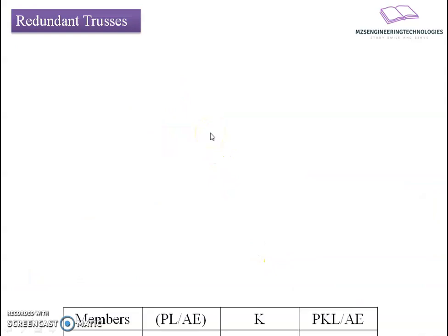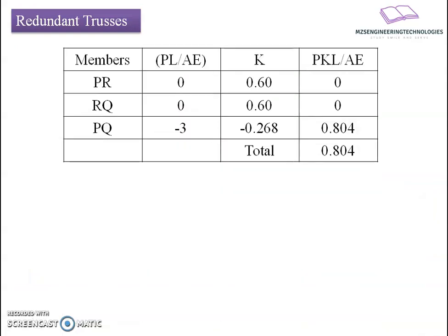Now we'll find the displacement at joint R due to the application of the unit load at R. For that we'll put the results into tabular format. The very first column will be members PR, RQ and PQ. Then I take the product PL upon A, which is the individual deformation of the member. For PR there is no deficiency observed, so I put 0.